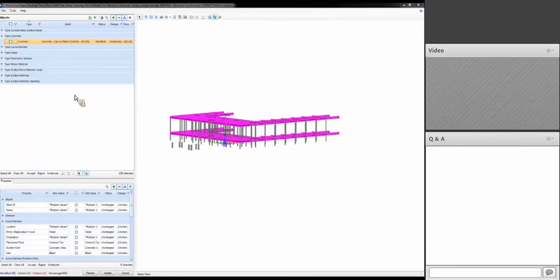Right now we're doing a compare on pretty much exact coordinates, or other types of values. But by allowing you to specify a tolerance, if your column is moved only 1/16 of an inch, an 1/8 of an inch, whatever, it won't show that as a revision, which is really going to reduce the clutter and provide for a smoother workflow.